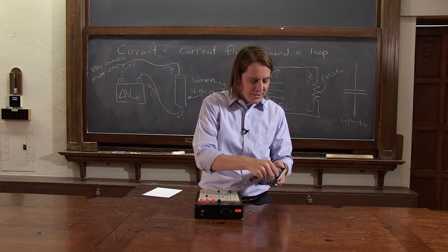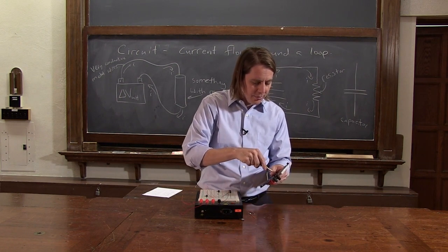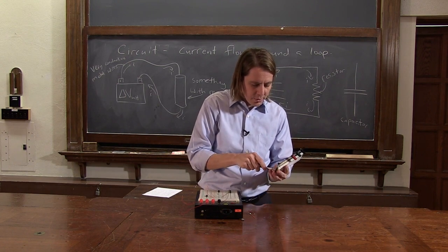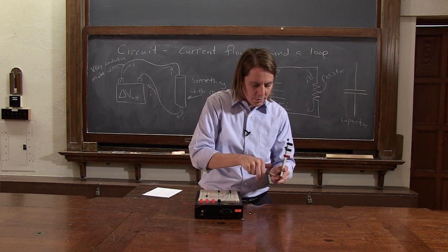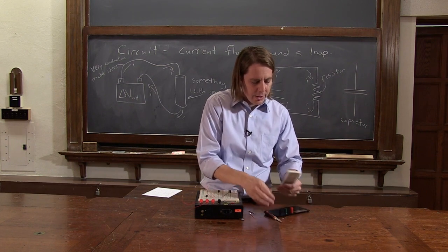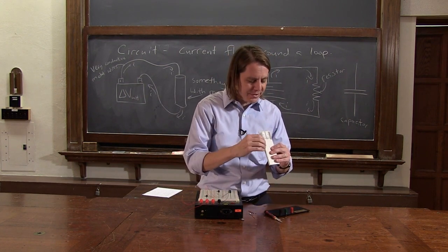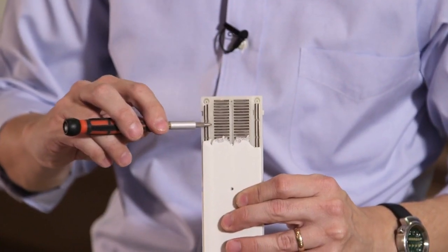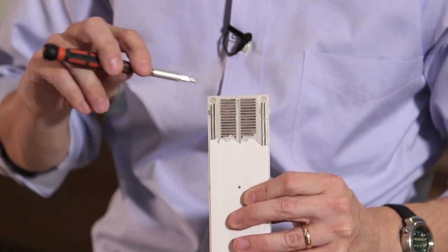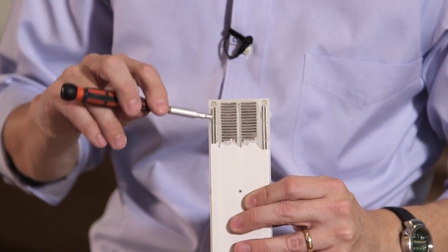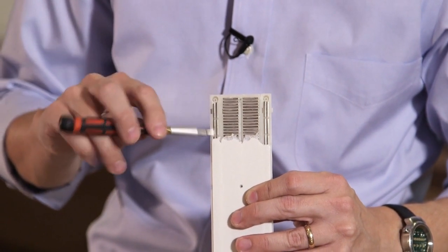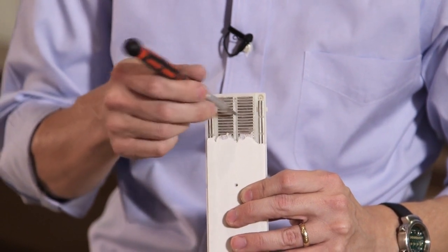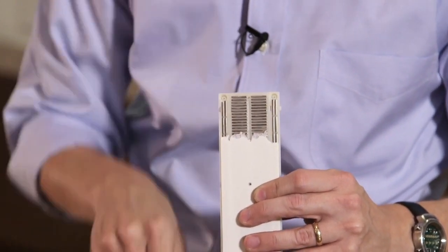Okay, so let me just take this thing off of its plate real quick. And one more. And I did it already ahead of time and peeled off some of this paper. And now you can see those little groups of 5, they are connected. This metal plate is what's connecting those 5 holes. And if you look down the side, sure enough, it's not just connected 5 at a time. This whole strip down the side is all connected together. So you could put your plus 5 volts there and put your ground there. And then when you want to connect to things, you do it in the small groups of 5 holes.